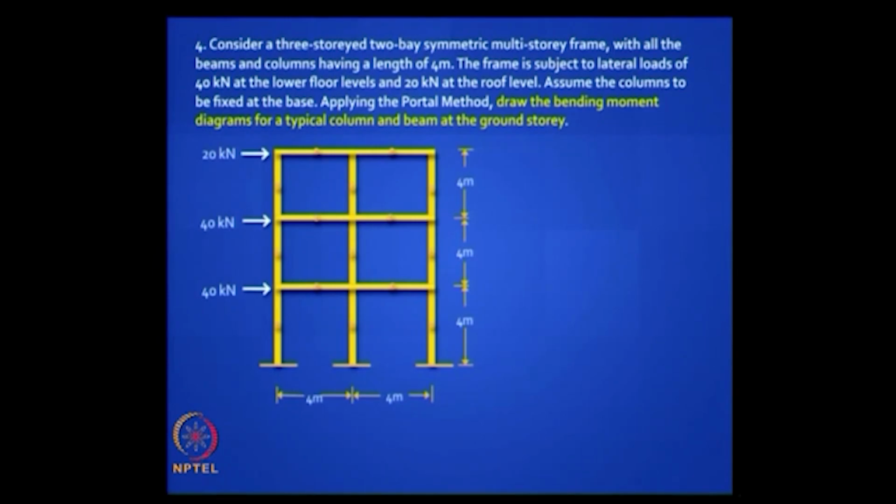Okay, first of all you have to get the story shears. We are doing the portal method, so these are the story shears. You don't worry about what's happening on top. Some of you insisted on solving the entire problem, finding the axial forces in the beams. Don't waste your time, and mine too.